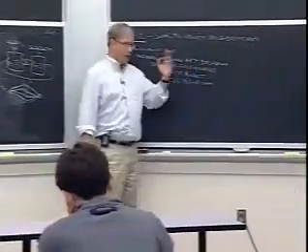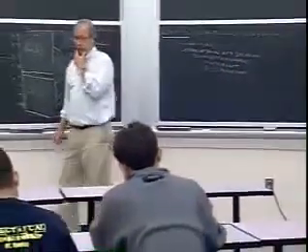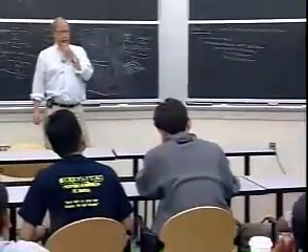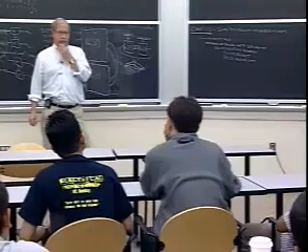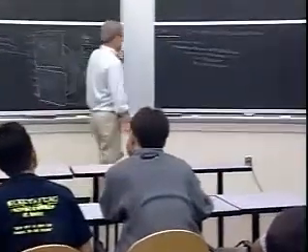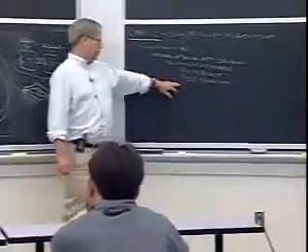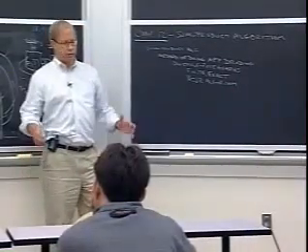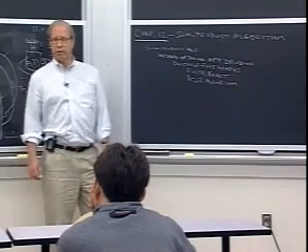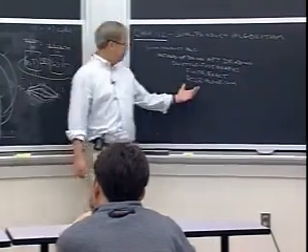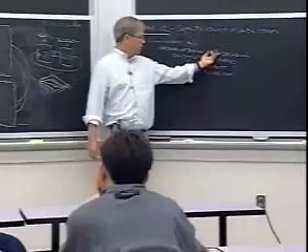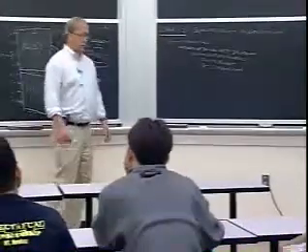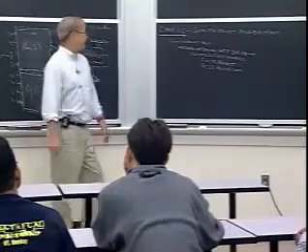widely used as a component of these decoding algorithms for turbo codes, in particular capacity approaching codes in general, because it's an exact way of decoding a trellis, and relatively fast, although we'll find it's more complex than the Viterbi algorithm. So if you were just interested in decoding a trellis, you would probably use the Viterbi algorithm, but you use the BCJR algorithm when you actually want to compute the a posteriori probabilities. And that's what you want when it's part of a larger algorithm.